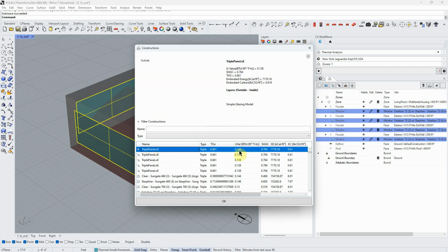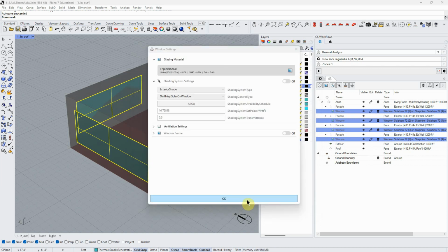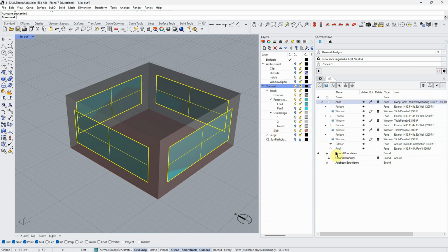But this is probably going to bite us because we're almost doubling the U value to get this extra solar heat gain. But again, this is way better than 1, which is what we had when we had the single pane of glass. Okay, so I'm going to select that, say OK here, and no shadings on. I'm going to run it.